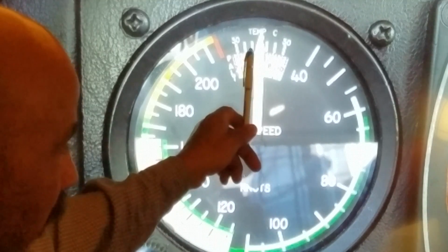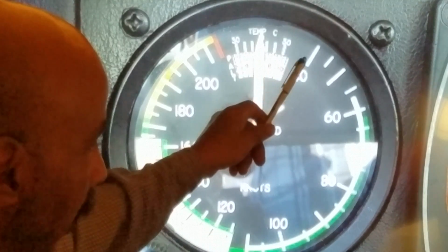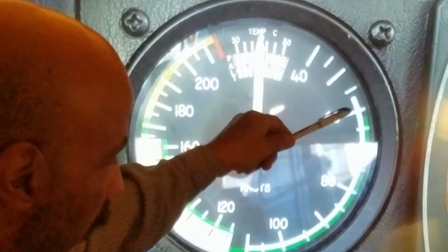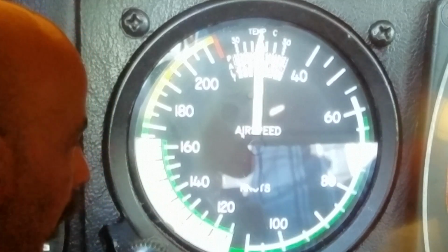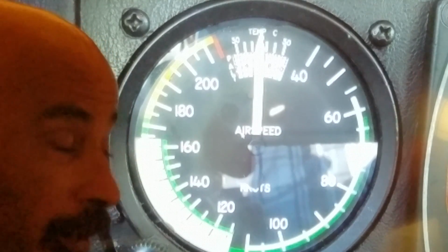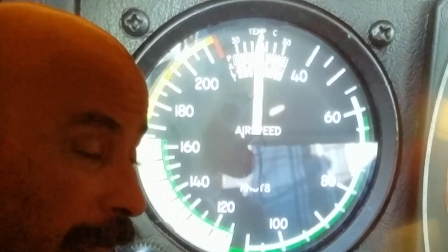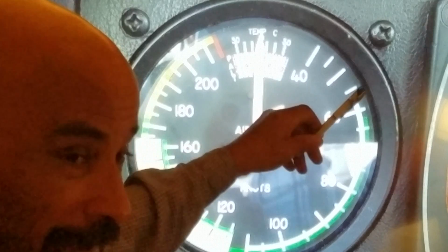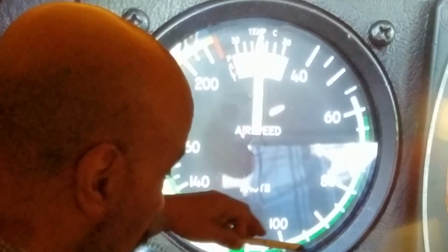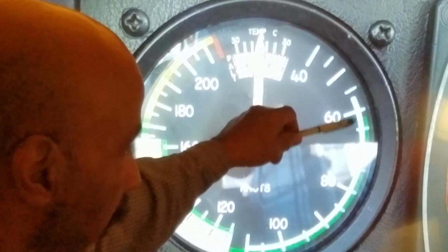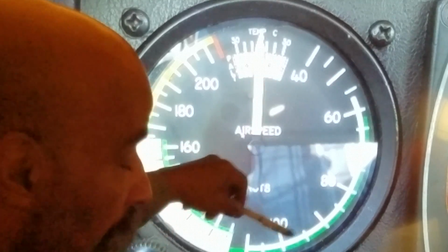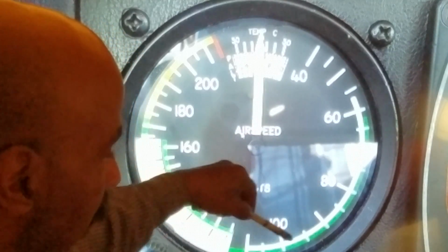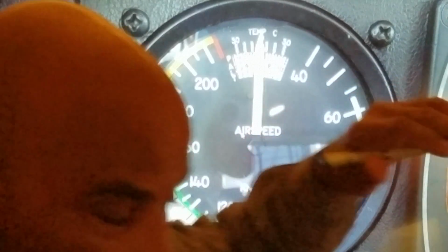As the airplane is taxiing or running down the runway and the gauge reaches this location, this particular position on this gauge, this is the stall speed, and sometimes people have used it as a takeoff speed for this aircraft or an aircraft. Might have the same color range markings, but they will be at different locations or different speeds for a different aircraft. But this white arc is a flap operating range arc.